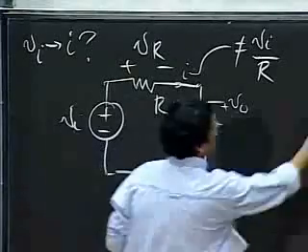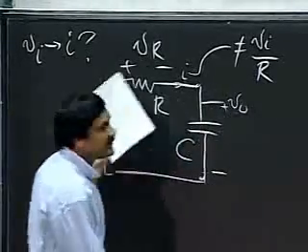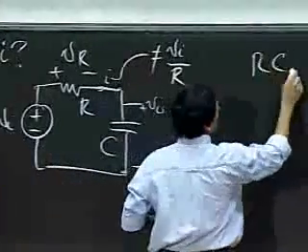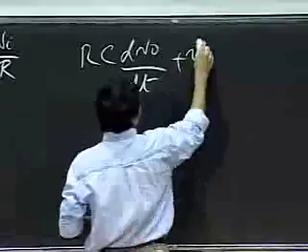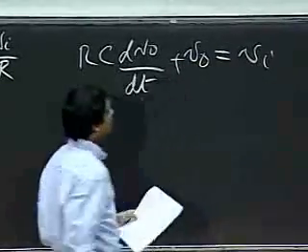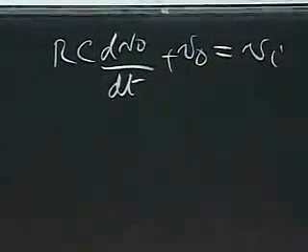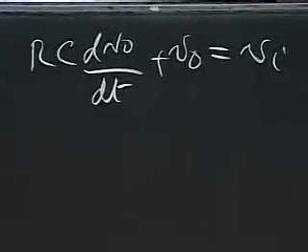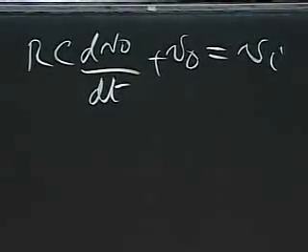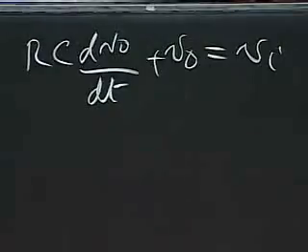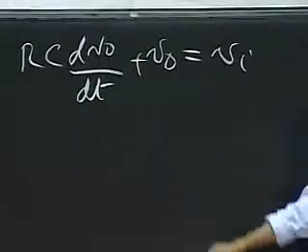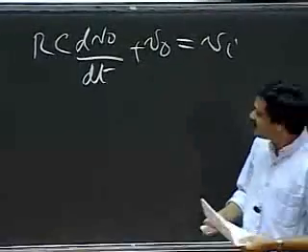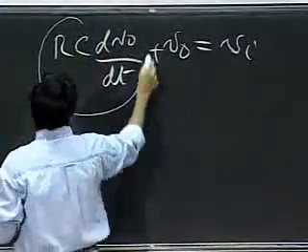And in fact, when we did RC circuits, you wrote this equation to represent the dynamics of the circuit, RC dV naught by dt plus V naught equals VI. We wrote down the circuit for a first order RC, wrote this equation for a first order RC circuit. Now, it does turn out, if we just wrap up on this wild goose chase that we went on, it does turn out that if this term here